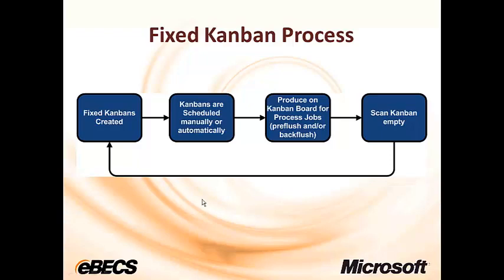So that was the fixed Kanban process. Basically, we created the fixed Kanbans. The Kanbans were scheduled, and like I said, that could either happen automatically or manually based on how you set the Kanban rule up. It's then produced on the Kanban board for process jobs. So then it's sitting in inventory, ready to use. And at the time when we consume that Kanban, we would scan that empty. So that's basically the fixed Kanban process.